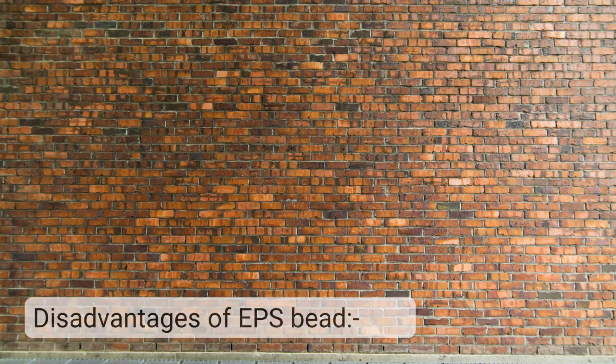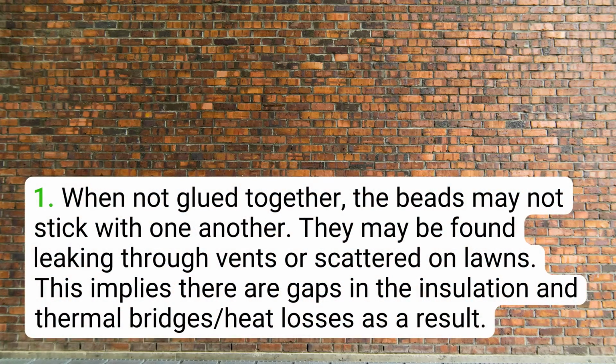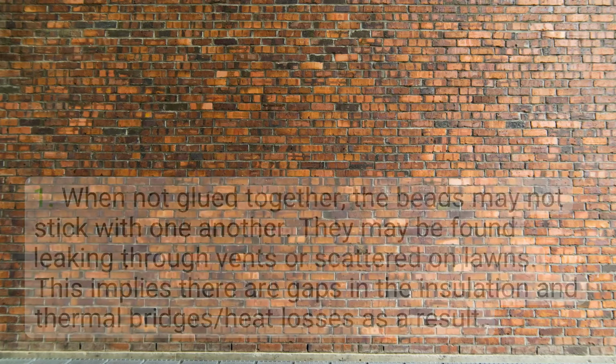Disadvantages of EPS bead. 1. When not glued together, the beads may not stick with one another. They may be found leaking through vents or scattered on lawns. This implies there are gaps in the insulation and thermal bridges, with heat loss as a result.